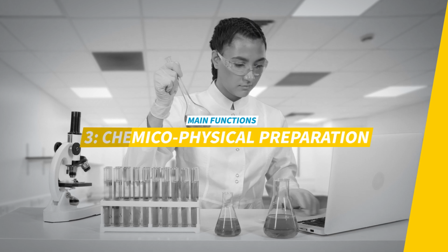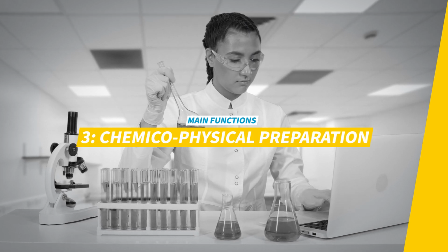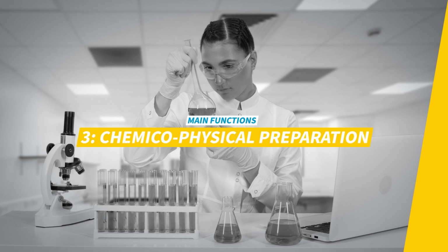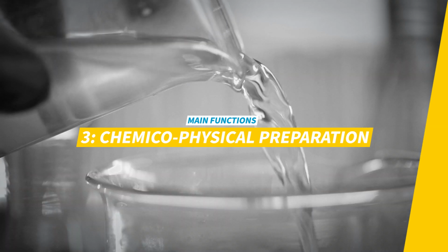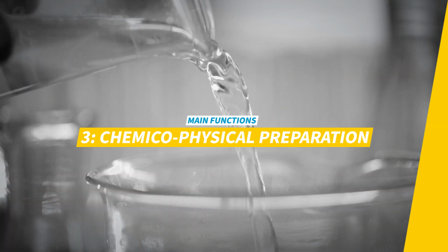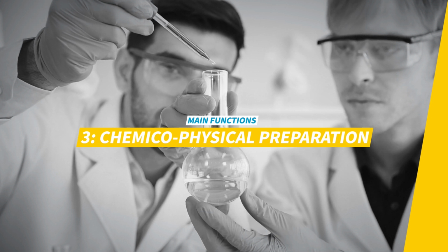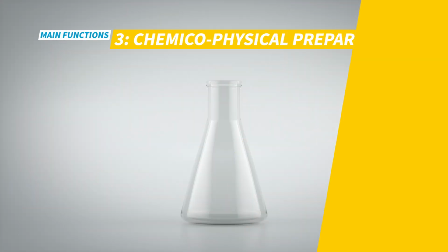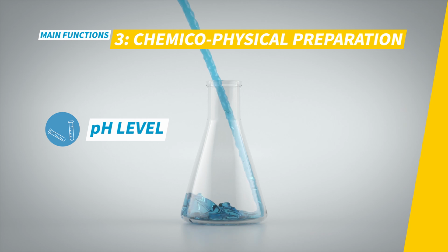To avoid corrosion and other potential damage, boiler feedwater must adhere to specific chemico-physical parameters. These parameters, or norms, are defined by the boiler industry, and they address several different aspects such as pH and dealing with dissolved gases. The pH value of the water, its level of acidity, must be restored to proper levels to avoid acidic corrosion. This is achieved by chemical dosing.